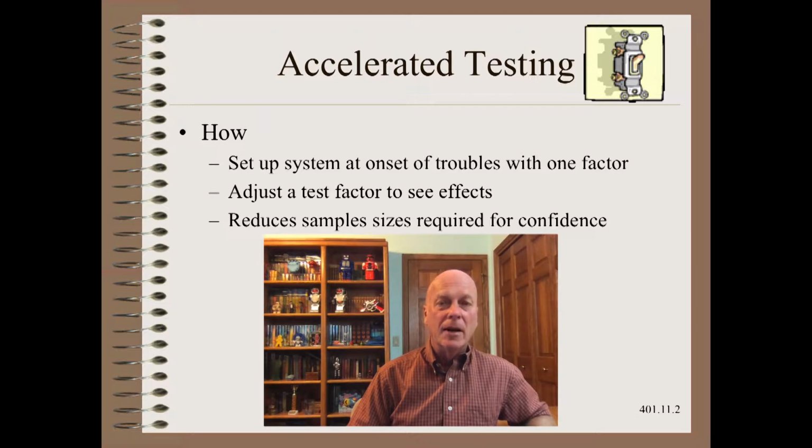Continuing with the web break problem, a break rate of 100 per roll instead of 1 per 100 rolls would not be practical to study. Even 10 breaks per roll would be too high, as the system would never really achieve a steady equilibrium. One way to adjust web break rates is to increase tension. Then the difference between suppliers, or a before and after roller alignment comparison, or any other operational maintenance change might be seen in a few rolls instead of a few hundred rolls.